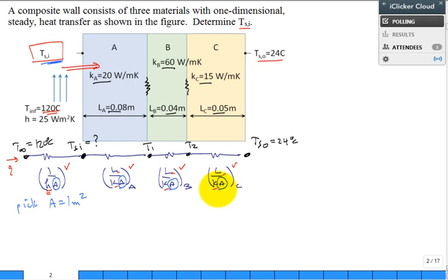Go ahead and compute all those resistors, sum them up because they're all in series to get an equivalent resistance, and then solve for the Q. This is kind of like first find Q, and then I could focus on only that convection resistor to find TSI. So, yes, sir?